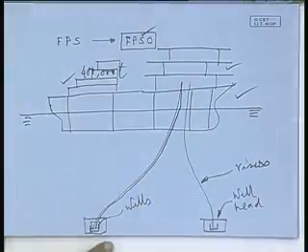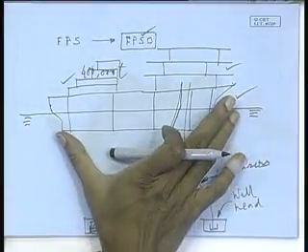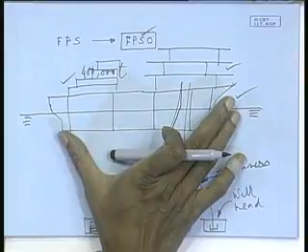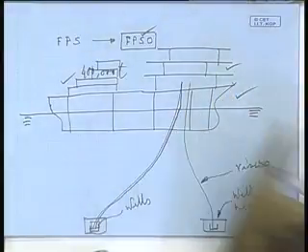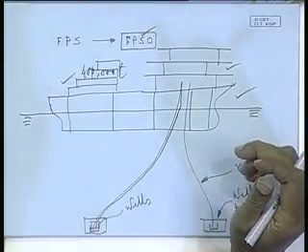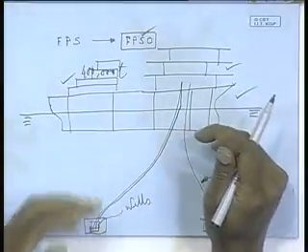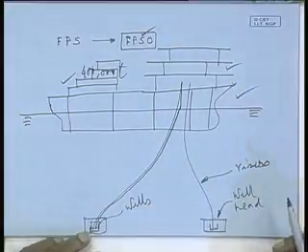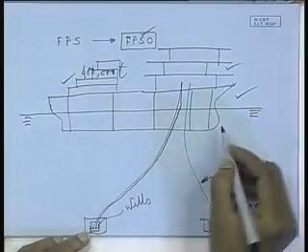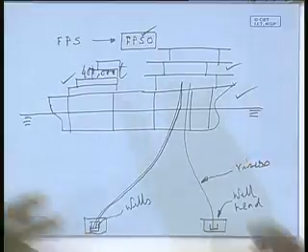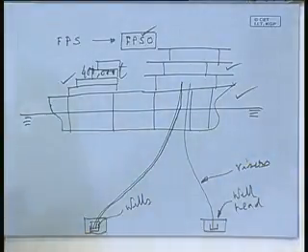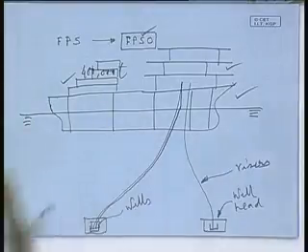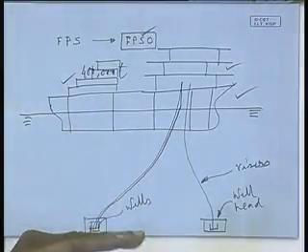And the other thing is, this FPSO is totally free. So, construction wise, there is no bending moment problem. In all the other structures, there was some movement of the structure, right? All those problems were there. Here it is only for exploration, you are only pumping oil. So, these pipes, risers, are flexible, right? But still it has to have some means of anchorage, some means of position keeping, such that it does not move out, does not sway out too much. If it heaves with the wave, no problem, because the pipes are flexible, you have enough length to take care of that.